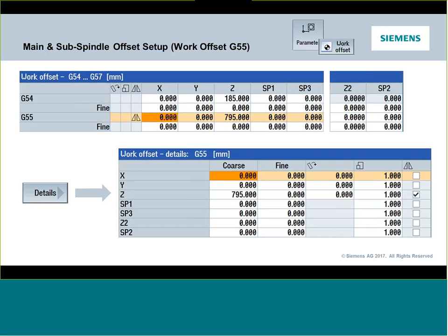But the important part here is not only the offset value, but how we're handling the Z axis. So if you go to the details of the work coordinate, it's easy to get to. When you're on the work coordinate level and you're highlighting it, there's a vertical soft key called Details. If you press that Details button, you're going to see this detail screen. What you want to do is put a checkbox in the Z mirror field.